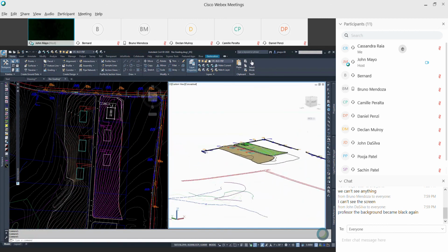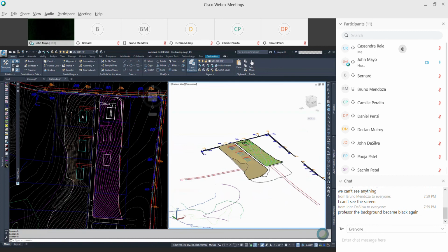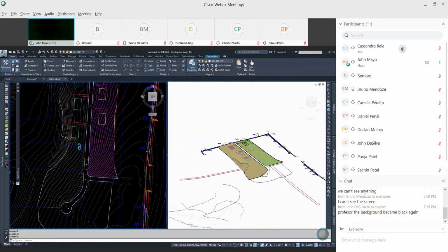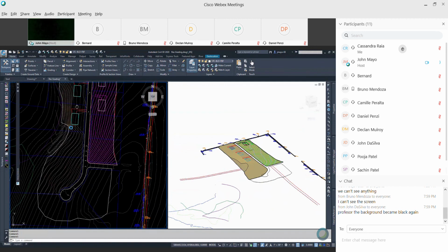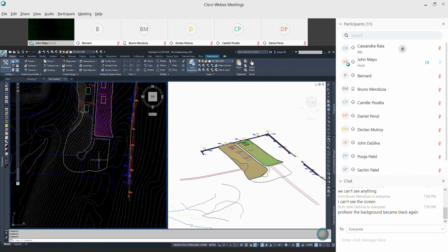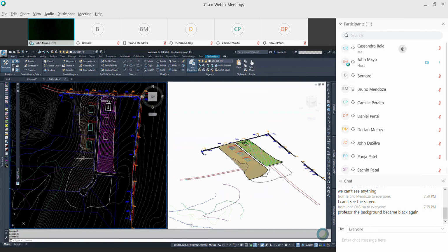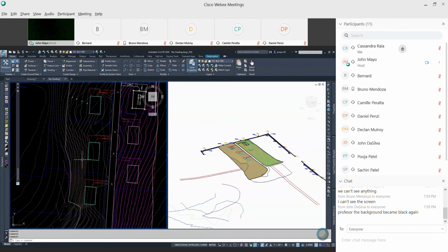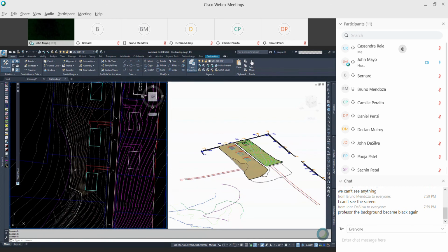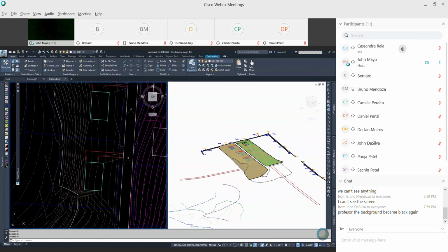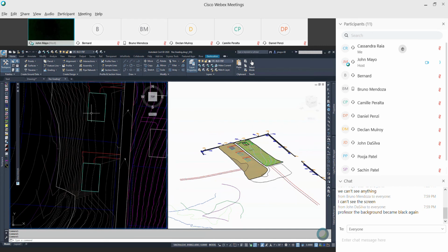So I would rough grade in buildings, driveways, all the way down, and this surface is going to here. You can then do another surface and do the buildings and driveways in these three lots. And I can finish up the buildings and driveways here. And then I would go around and look at other specific detailing I could do. But once I got these in, I would better see where I would need walls, especially once I adjusted this and this for a walkout basement, right?